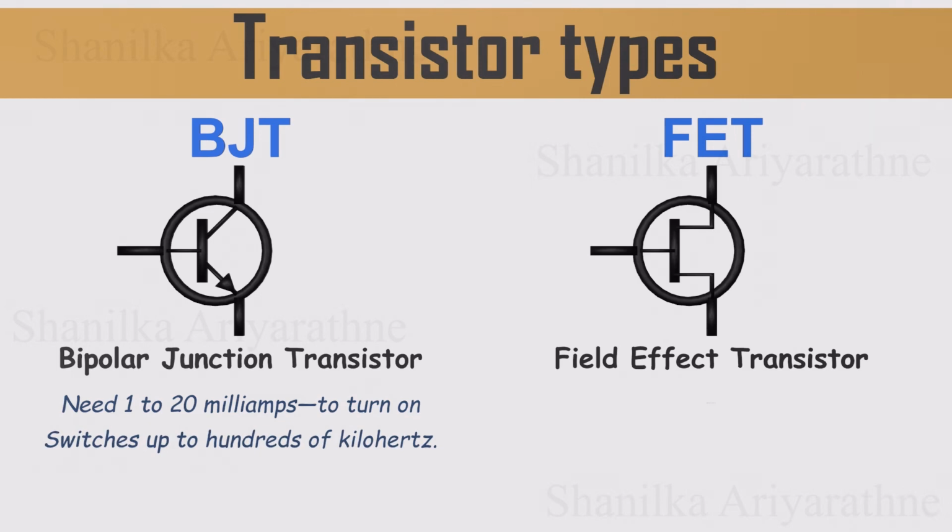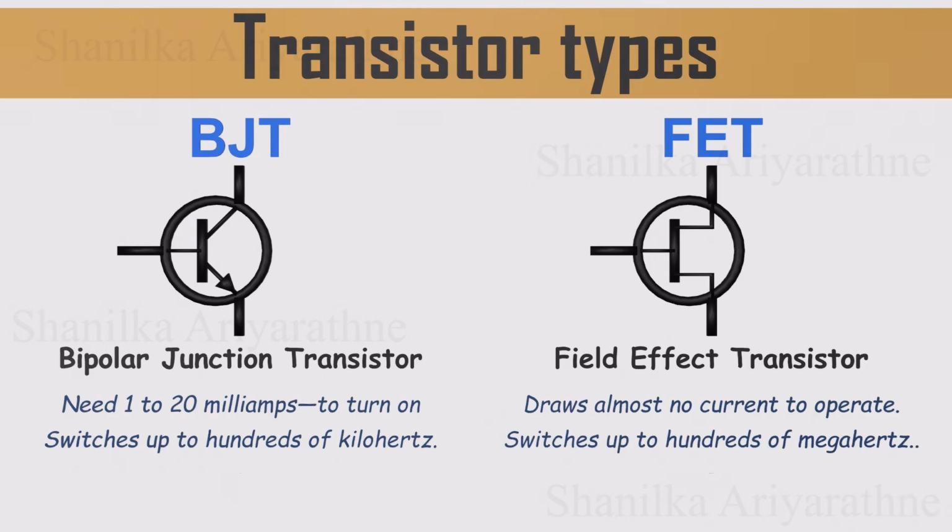These are a bit different. They're controlled by voltage rather than current. That means they draw almost no input current at all, which makes them much more efficient. As a result, FETs can switch way faster, often in the tens or even hundreds of megahertz.